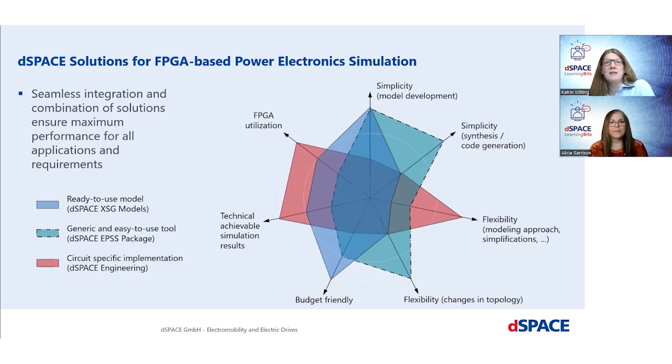In this case, deep knowledge in modeling, FPGA programming, and HIL simulation is required, but of course, extremely fast and precise models result. Another approach is to use ready-to-use models like the XSG Electric Components library from dSPACE. In this case, they can be easily integrated into existing applications and less special knowledge is required, but the variety of topologies is limited to the main use cases which are frequently used.